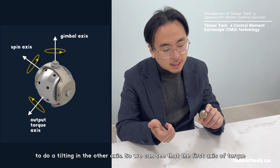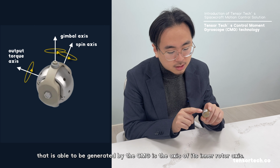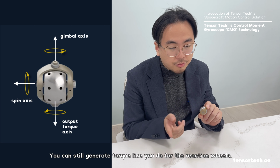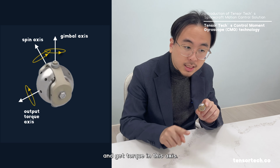So we can see that the first axis of torque that can be generated by the CMG is the axis of its inner rotor. You can still generate torque like you do for the reaction wheel: you accelerate or decelerate the rotational speed of the rotor and get torque in this axis.